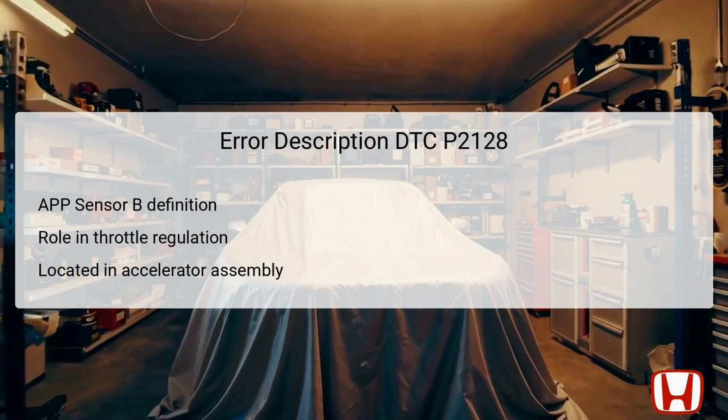The voltage reading should not exceed normal thresholds. Otherwise, it may trigger the DTC P2128. Several possible causes can lead to the triggering of DTC P2128. Firstly, the most direct cause could be a faulty APP sensor itself, which may not be providing accurate readings due to wear and tear or internal failure.